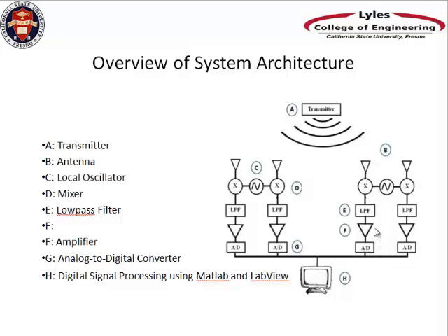The reason we're using the amplifier here before the DAQ is that the DAQ itself has a noise signal, so to get rid of the noise we're using the amplifier. And after the conversion, the digital signal is going to go to the computer, collected by LabVIEW, and then LabVIEW is going to send the data to MATLAB to do some calculations to find the location of the item.